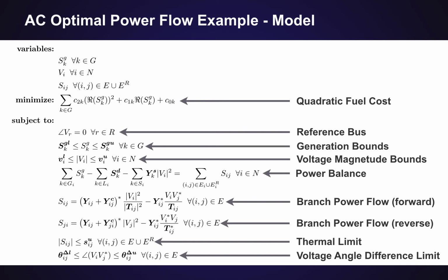It's worth noting here that we didn't treat DC power lines, HVDC, but we do implement the version of that which is from Matpower, and it's a fairly simple model where there are two power sources at the two buses, and they're linked together through a simple constraint which can account for some linear losses on the DC line.